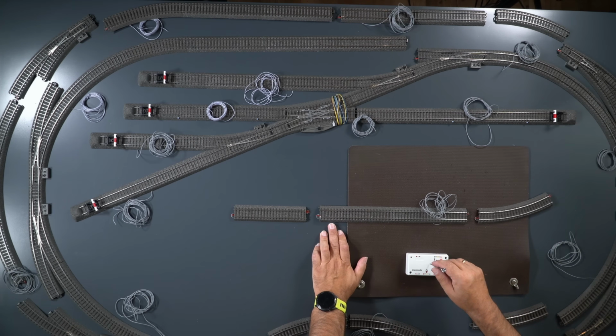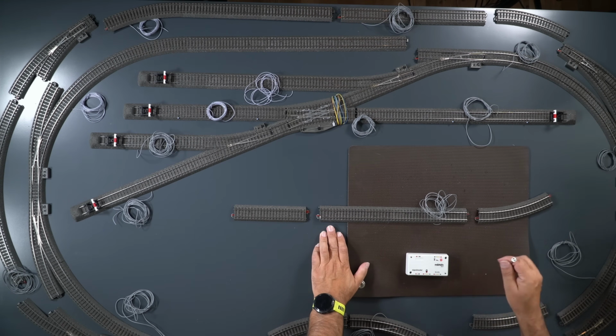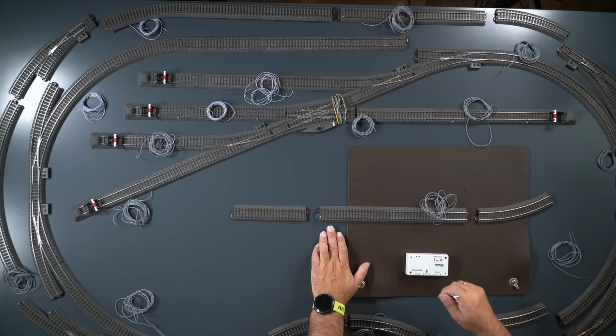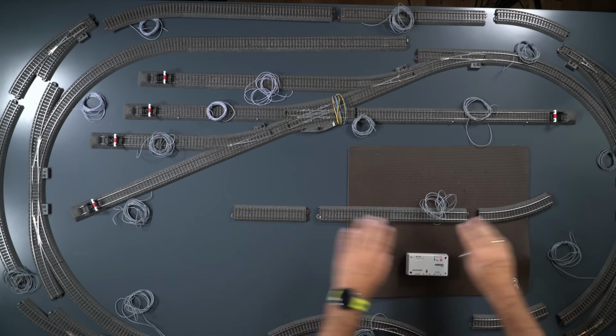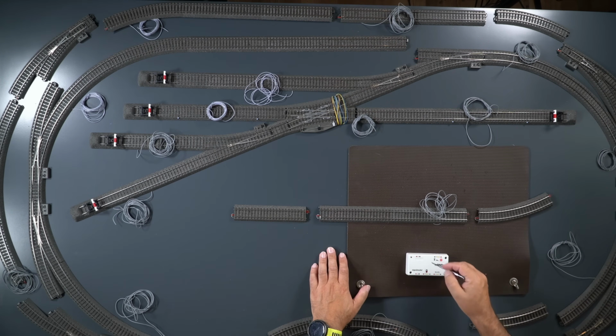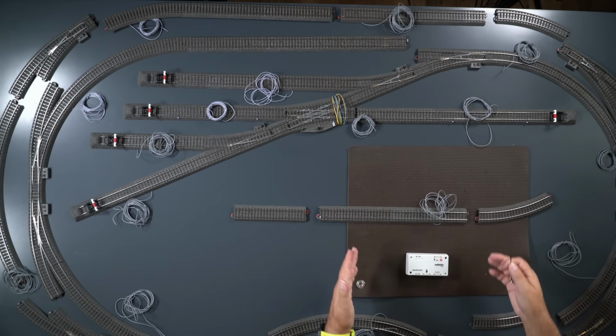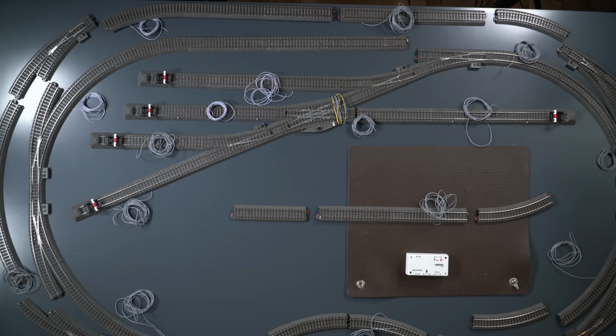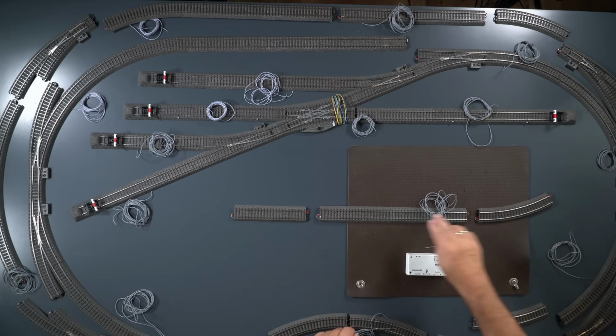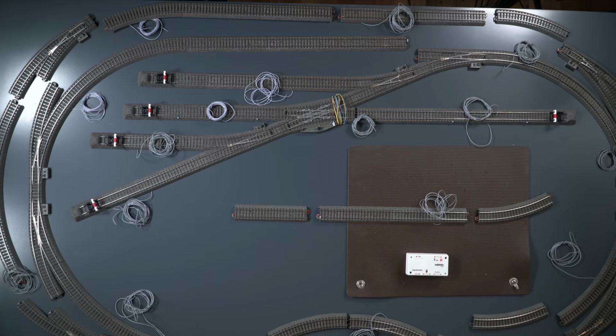When a green signal is switched on again, indicating that it is now safe to proceed, the signal module will release all three of these sections and switch them back to their normal track power state. The locomotives will then resume their journey as usual, continuing along the track. For that, of course, I now have to solder a red wire here, here and here so that I can later connect it to the braking module.